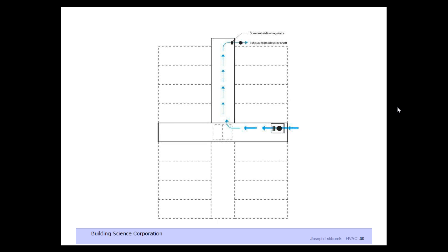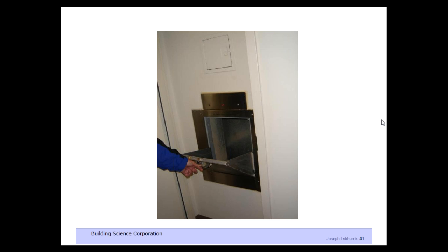As strange as it seems, some people are determined to overventilate the corridors and overpressurize the corridors, and that's going to require preconditioning of the air because it's almost 100% latent load, and there's no sensible load in these corridors because they're not usually seeing any exterior walls. This is not an easy answer. Trash chutes, they've got to be negative. Got to suck.